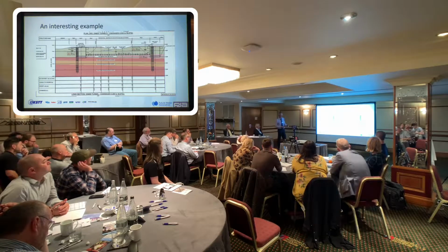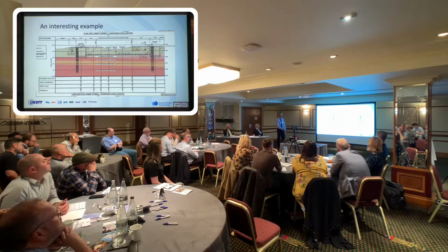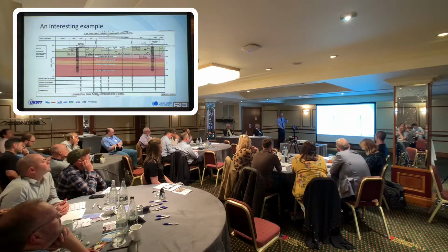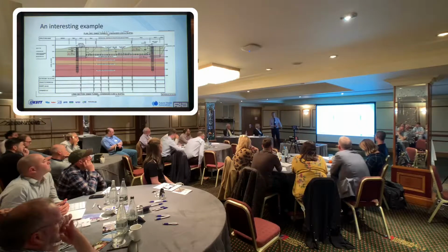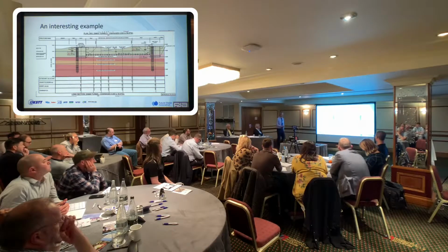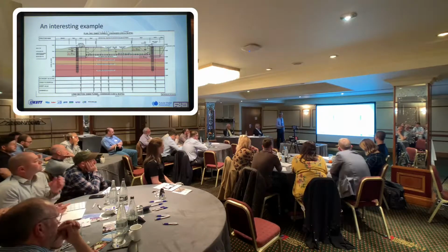We then prefabricated the reinforcing cage, divers cleaned out the base, we dropped the cage in underwater, and then we poured the base plug underwater. That allowed us to thin the slab to an extent that we still had sufficient cover in the alluvial deposits to make the settlement calculations on the railway work. Similar thing on the reception shaft.